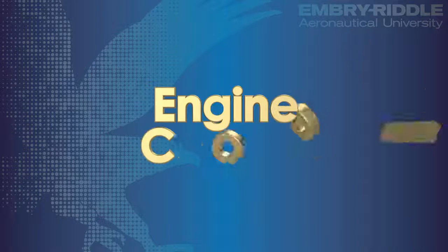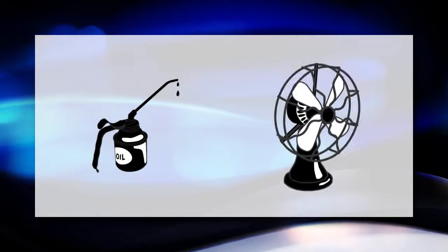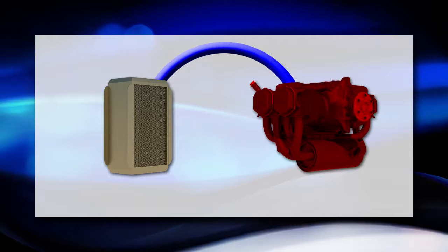Even when the engine isn't detonating or experiencing pre-ignition, the temperature of an engine can get quite hot. Like car engines, airplane engines have a cooling system in order to prevent engine damage or engine failure. There are two major ways we cool our engine: oil and air. Oil passes through an oil cooler and proceeds to not only lubricate, but also cool the engine.